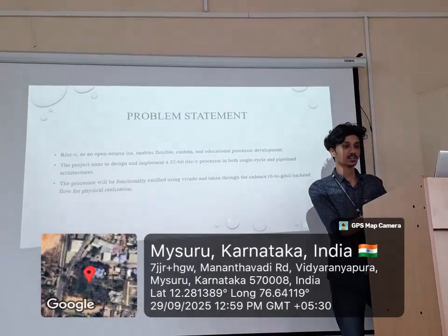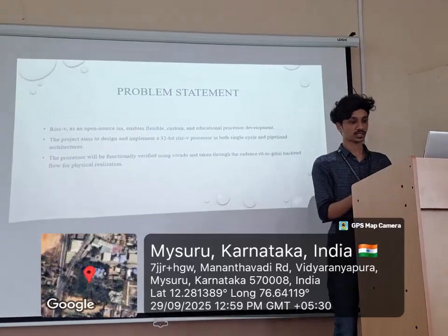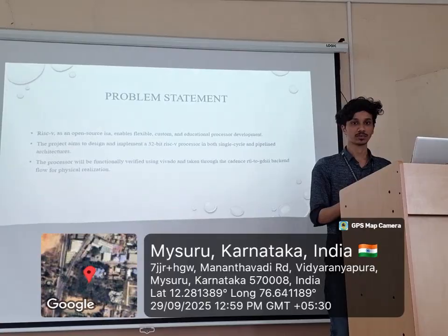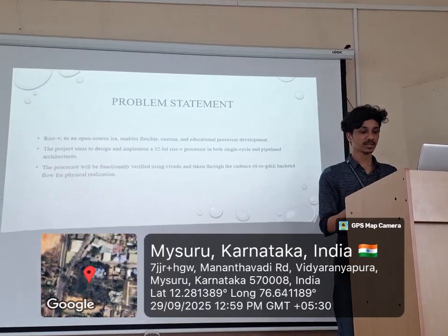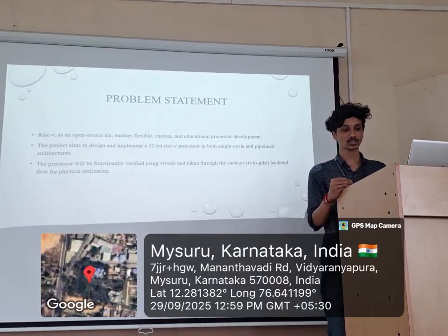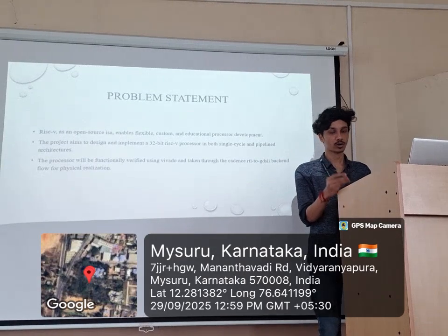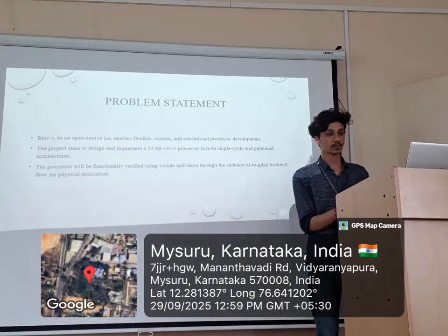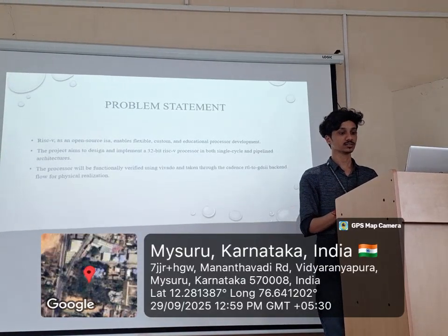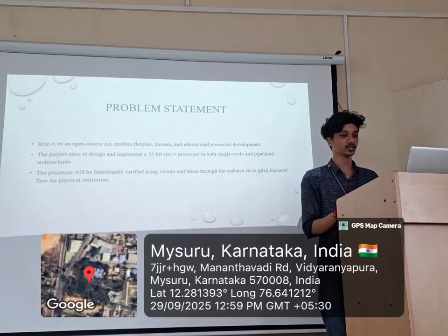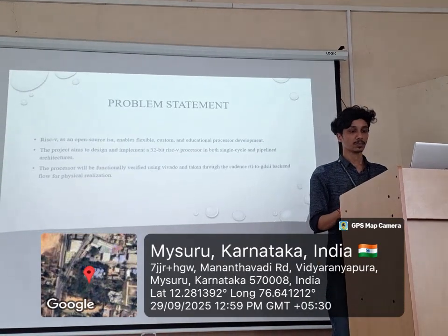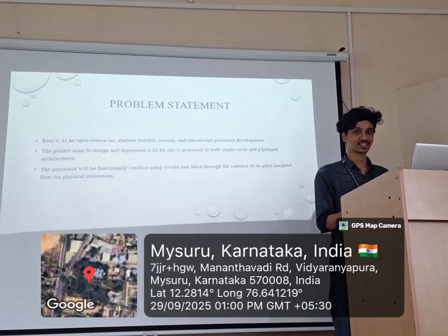Single cycle is where each instruction completes in one clock cycle, offering simplicity but limited performance. Whereas pipeline breaks instruction execution into multiple stages to improve the performance and throughput. Functionality is verified using the Xilinx method and then we take the design through the RTL to GDSII flow for the complete physical realization, preparing for potential fabrication.